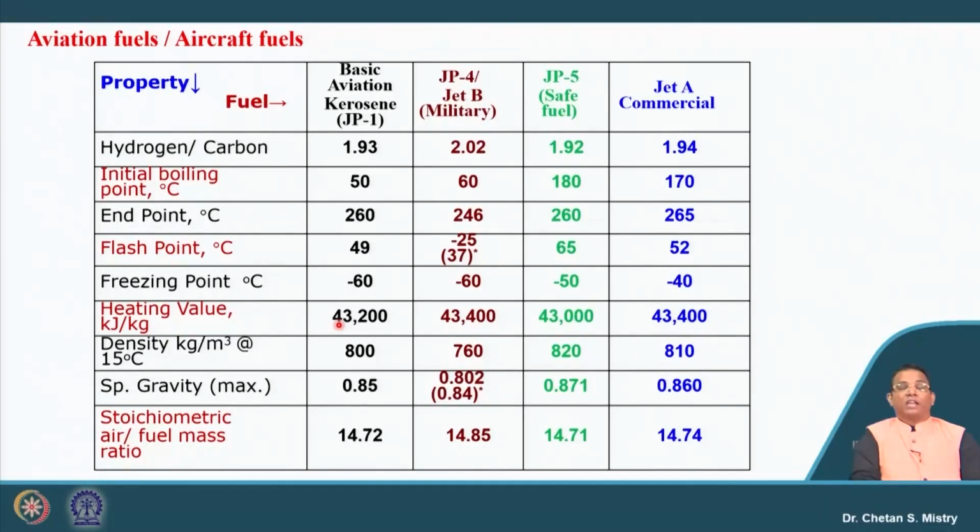Then we took the control volume approach and tried to analyze it. Later we realized there would be an efficiency term coming into the picture. At the same time, the ideal and actual conditions differ because of the pressure drop inside the combustor.